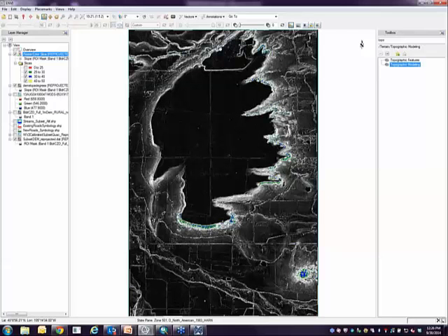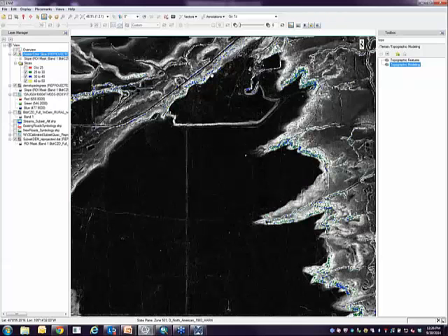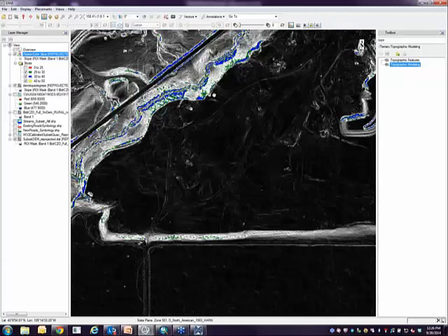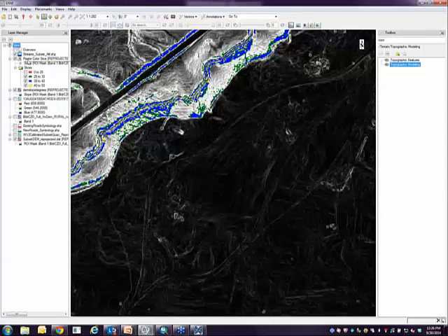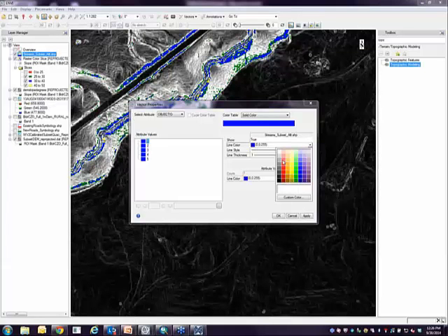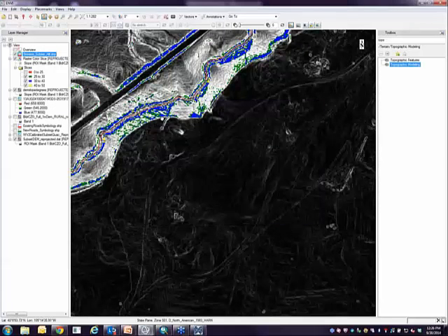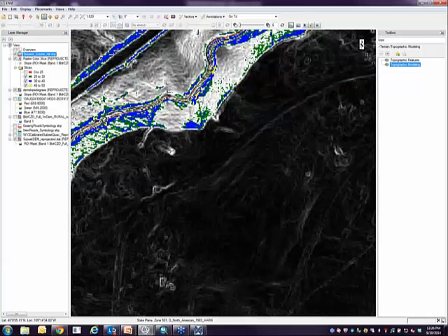So if I zoom into this area, and I'm going to put my stream up here, maybe I'm going to turn it red so you can see it. Make it a little thicker. Okay, so you can see my stream. Some of the areas have a steeper slope, especially these yellows, 40 to 50-degree slope, where I'm going to need a wider vegetative filter buffer.